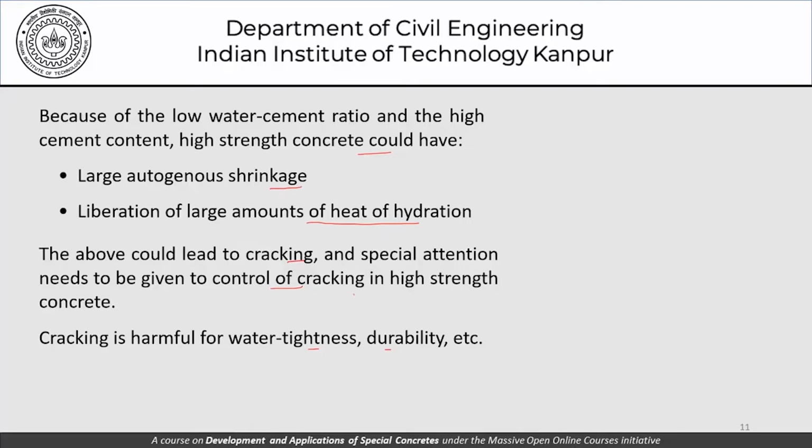So it's very nice to be able to use high strength concrete or develop high strength concrete, but along with it there are some downsides: increase in autogenous shrinkage, liberation of large amounts of heat, and the resulting cracking. So we have to be careful about that.